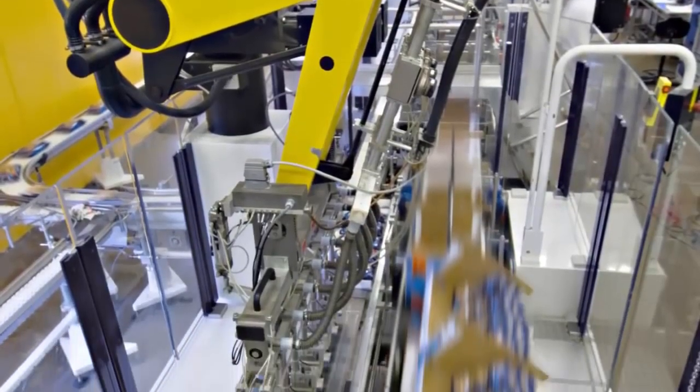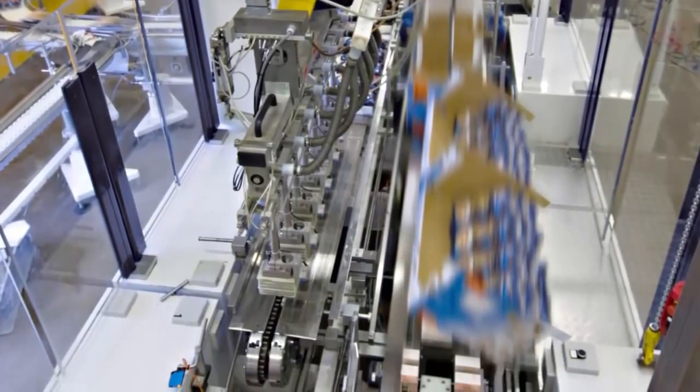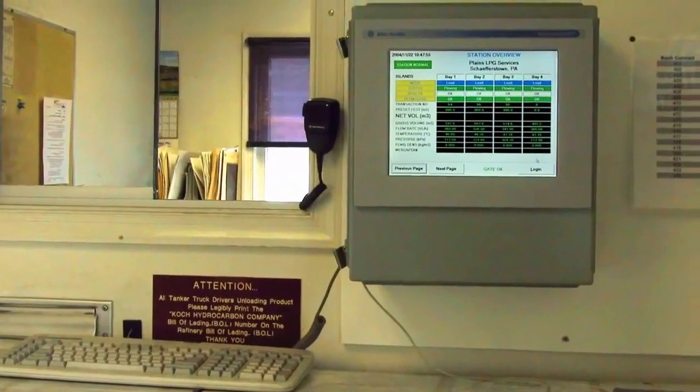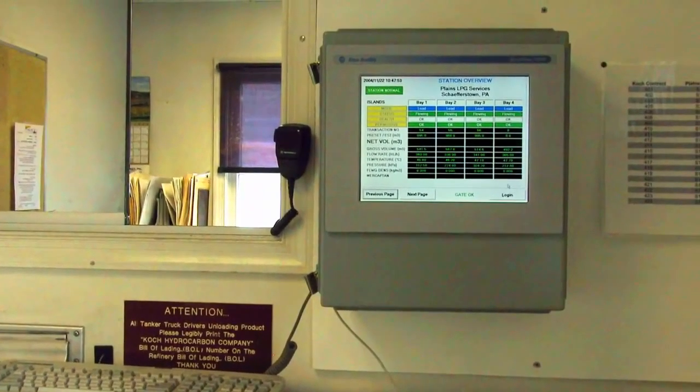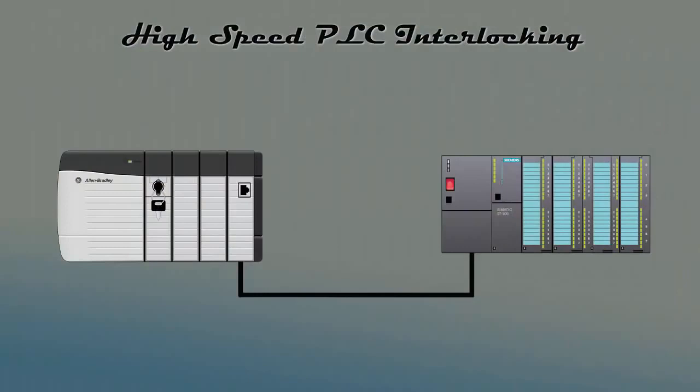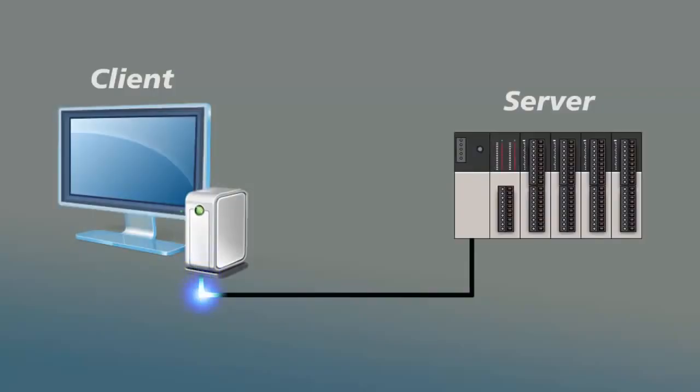I/O message communications are given higher priority by the processor, while client-server data messaging are given lower priority. I/O messages are designed to run at regular time intervals, meaning the communication speeds are consistent, whereas regular data messaging speeds are dependent on the availability of unused processing power.